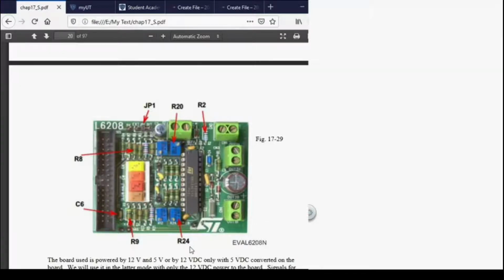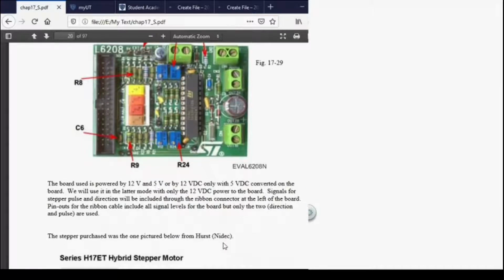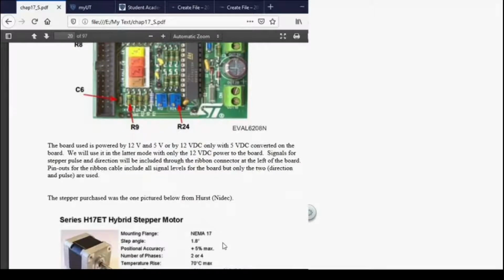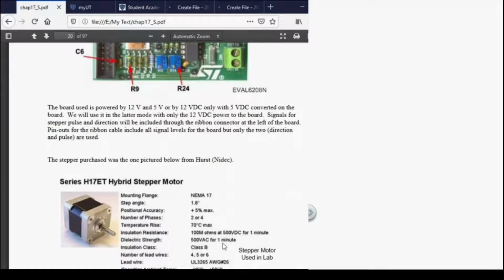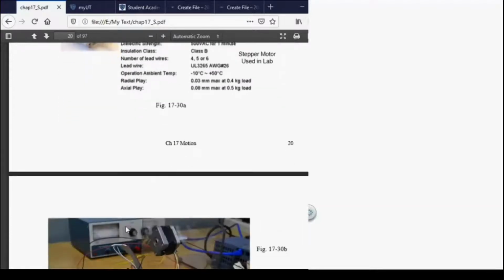So basically, the stepper motor receives pulses from this card, which receive pulses from the Siemens output controller. So that's how that's done. And we would use the motor control blocks from the Siemens Corporation for their controls. So basically, it's an open loop system. We control a little stepper motor like this, and we basically turn the shaft, and we just notice when it's in a certain position. So many pulses would turn one revolution of that shaft, and that's all we were doing. And that's how this is wired.